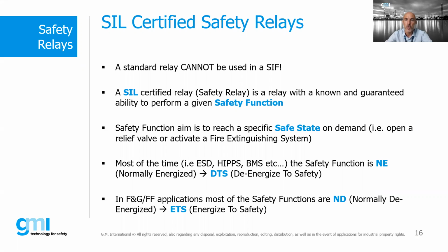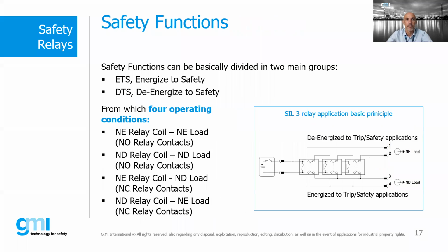The safety function is normally energized. So in case of safety, you want to de-energize to safety. So for ESD, basically the load is energized, and in case of safety, you want to open. The other way around, for fire and gas, the application is normally de-energized, and you want to energize in case of safety. Those are the main functions we are talking about today. So energize to safety or de-energize to safety are the two components we already introduced to you.